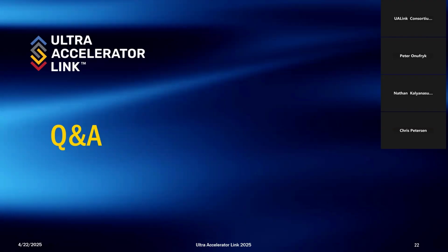Thank you, Peter. Our next question, how does UALink compare to or differ from CXL? So I could take a stab at this one. I think the key here is, as Nathan already mentioned earlier, UALink is not cache coherent, whereas CXL is cache coherent. So that is one significant difference. They are certainly both memory semantic, but the other key difference is that CXL is built on top of the PCIe stack and physical layer, whereas UALink has the flexibility to also run on top of the Ethernet physical layer, which certainly provides an increase in the per lane bandwidth.